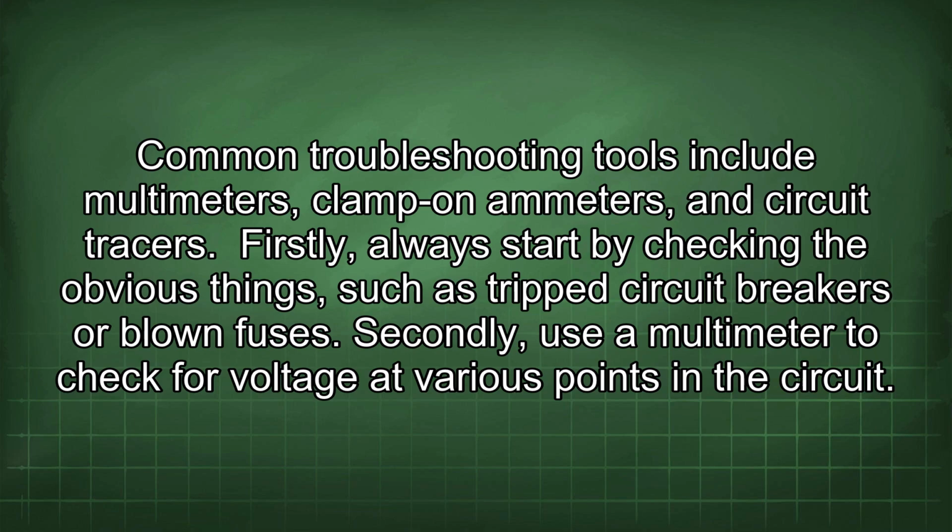Common troubleshooting tools include multimeters, clamp-on ammeters, and circuit tracers. Firstly, always start by checking the obvious things, such as tripped circuit breakers or blown fuses. Secondly, use a multimeter to check for voltage at various points in the circuit.